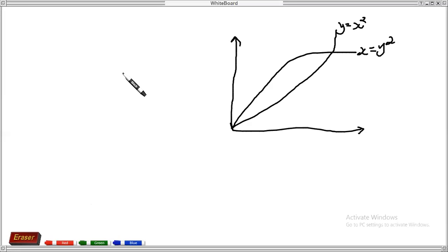So what we have here, you want to find the centroid on the x-axis and also on the y-axis. Again, you use similar equations. x bar equals the integral of x_c dA over A, because now it's an area that we're talking about, not the length.